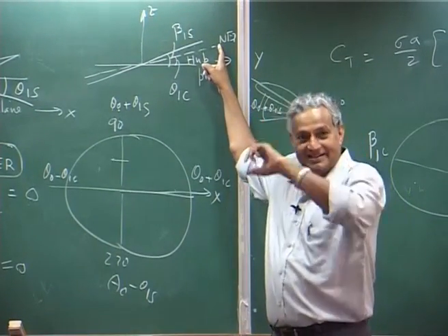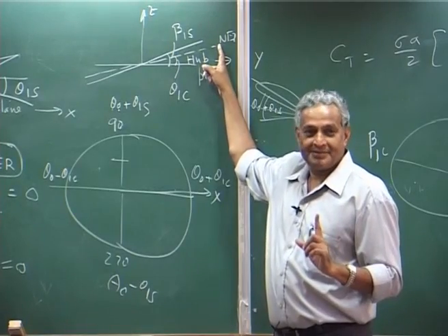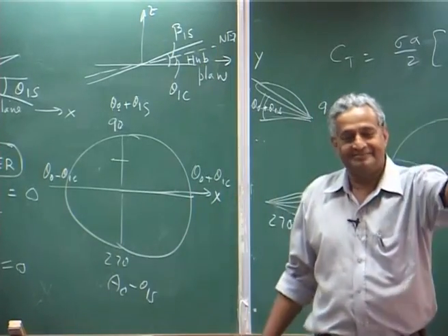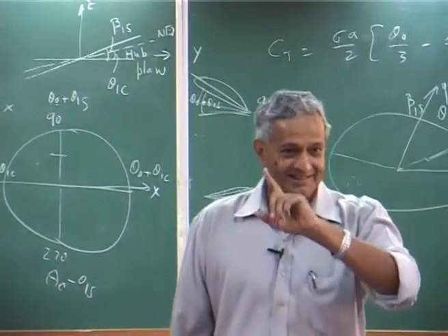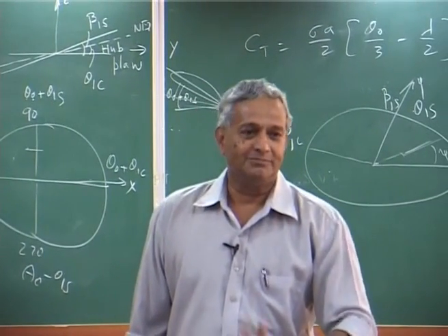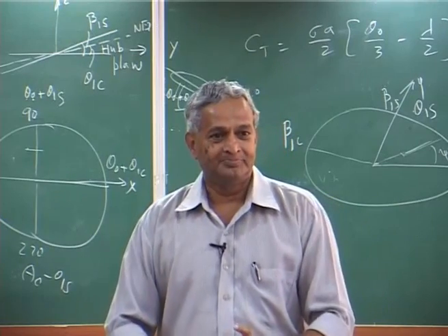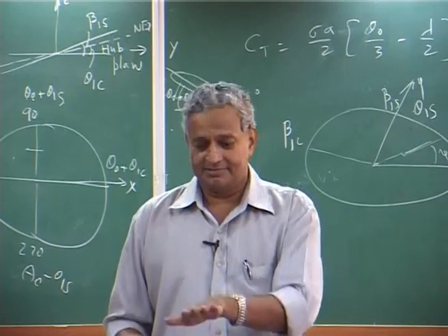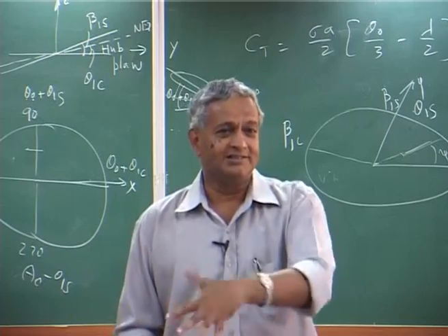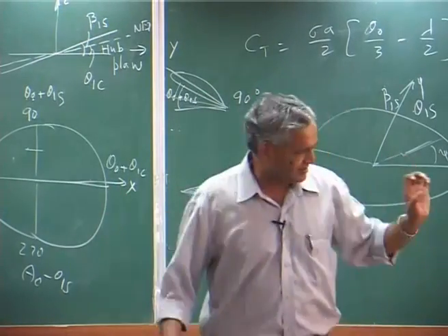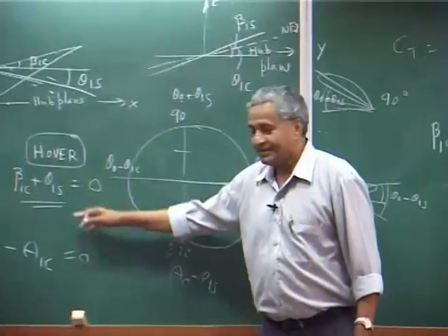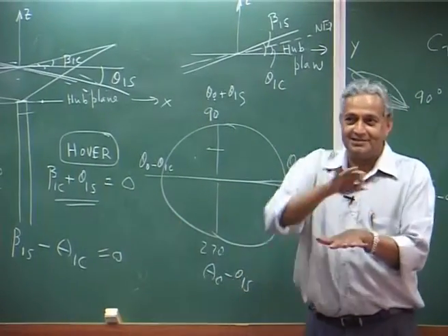And because of the blade dynamics, the tip path plane tilts. Okay. He does not tilt the tip path plane, he tilts only the no feathering plane, that is the swash plate. He just tilts laterally at any orientation, and as a result, because you know in hover, in the highly simplified case, they are parallel. So, wherever he tilts, that also goes there.